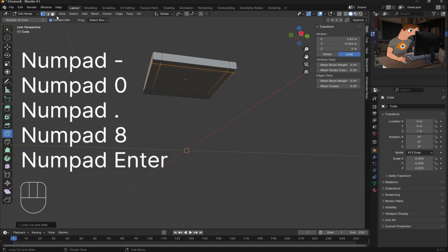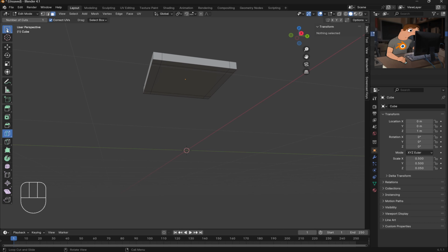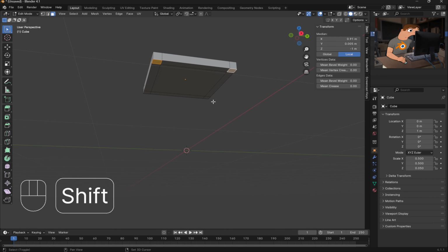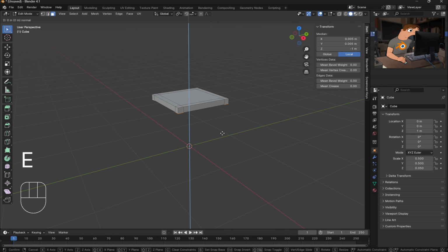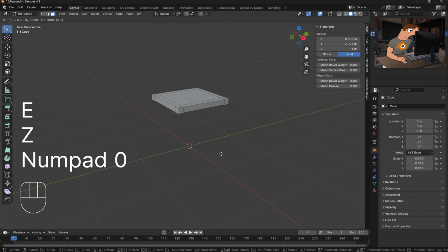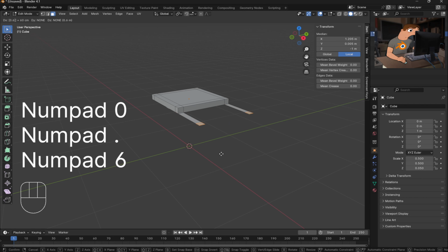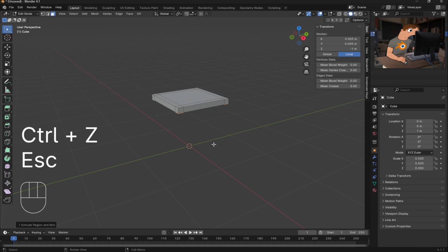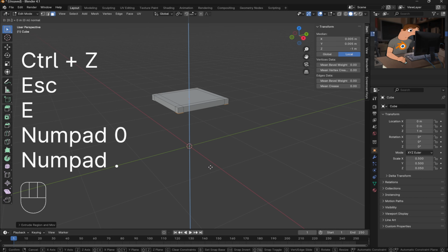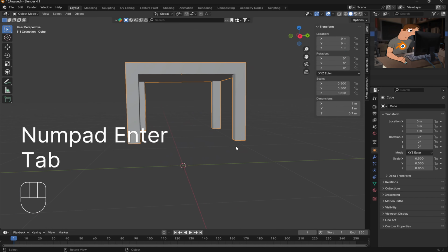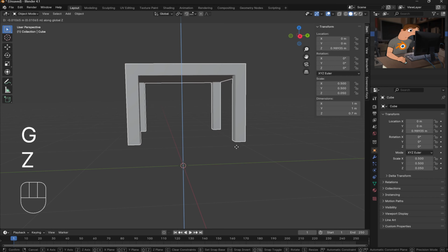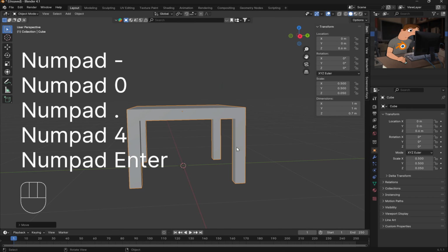Go to Face Select and select the 4 corner faces. Then press E to extrude and press the Z axis to specify the axis of the extrusion. Type the minus 0.6 value to have this extruded on that set distance towards the ground plane. The table is on the ground floor; select it and translate it to 0.4 meters on the Z axis.